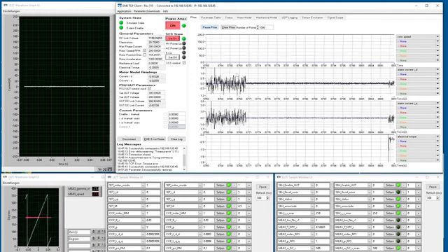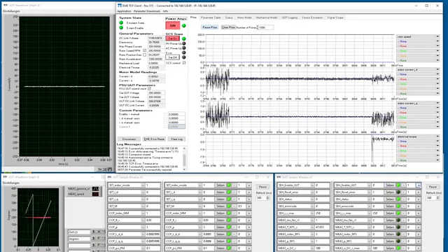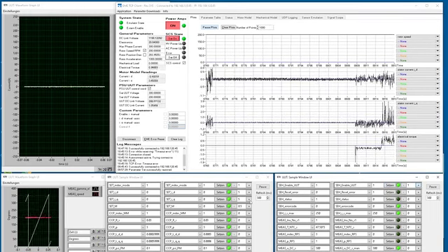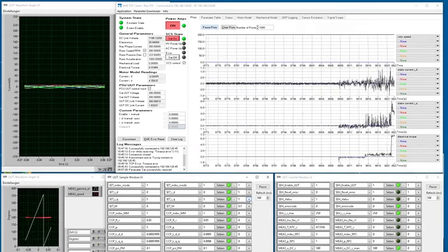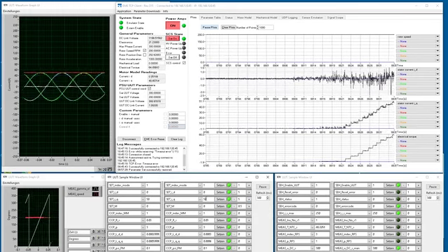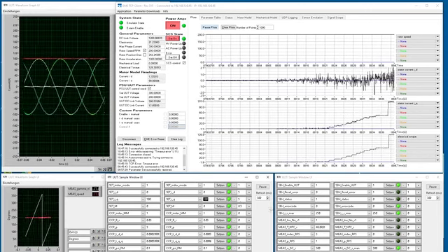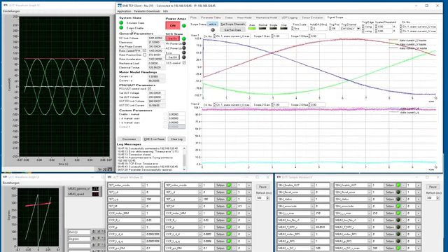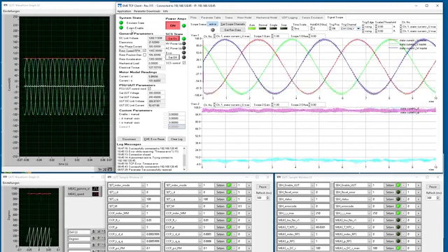Firstly, we would like to perform the current control mode of the inverter. The initial rotor speed is set to 200 RPM. The inverter now is enabled. Then the Q current set point is increased from 0 to 100 ampere. Afterwards, the rotor speed is increased to 1000 RPM.